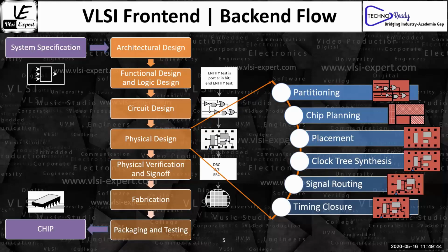Partitioning: the moment I say there are 10 blocks, that means I did the partitioning. There is a clubhouse, there is a swimming pool, I did the partitioning. That's on the basis of functionality, on the basis of your domains, like a power domain or clock domain, or on the basis of the complexity of your design. Partitioning is all about how you're going to simplify your design.